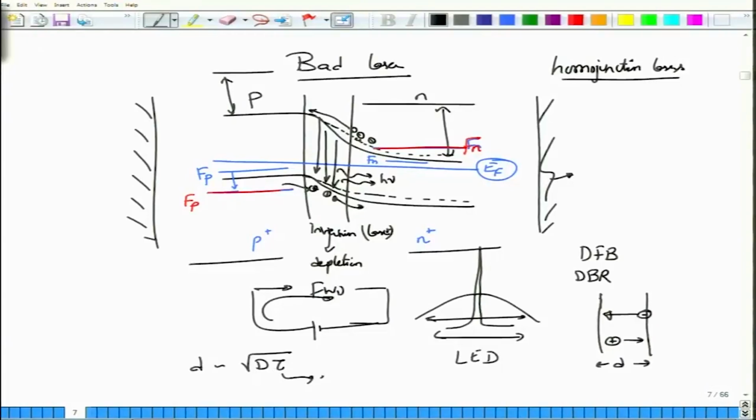So, this is the diffusion constant and this is the lifetime constant, which is usually measured experimentally, and this diffusion constant is determined by rather complicated calculations which we do not want to go into, but the idea is that the length over which the inversion layer exists is actually uncontrollable, because these quantities are usually not in our control, they are material properties and they are also temperature dependent. So, it is uncontrollable and it is actually very thin. Okay. What is the implication of a thin layer? In fact, this layer will be approximately about 1 micrometer at most, about 0.9 micrometer is typical.